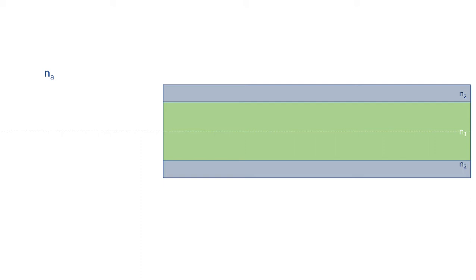Let us consider light entering into the OFC, undergoing refraction at the ambient medium core interface. If it strikes the core cladding interface at critical angle, the angle of refraction is 90 degrees. That is, the light grazes through the boundary of core and cladding, which is not usable for communication. Let us take this path as reference and consider another pathway between the axis and the reference path.